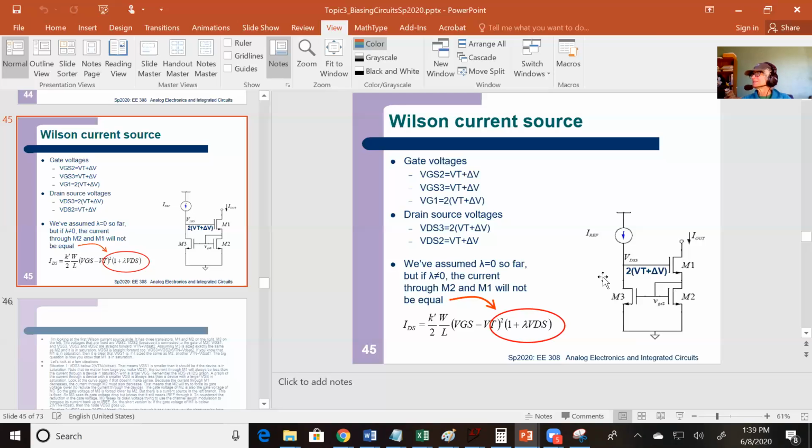Yeah, cascading just takes up, again, you need all your transistors in the forward active region, or saturation if it's a MOSFET. So it takes up a little bit of headroom, but this does too. So really, cascading is, if you need a really good current source, just cascade some transistors and it's better than the Wilsons. But I wanted to bring up the name.